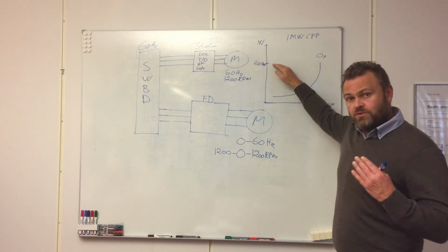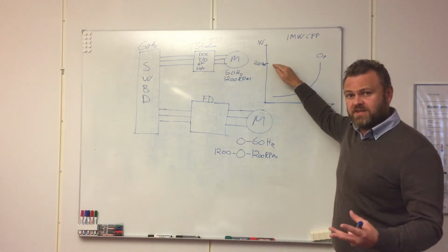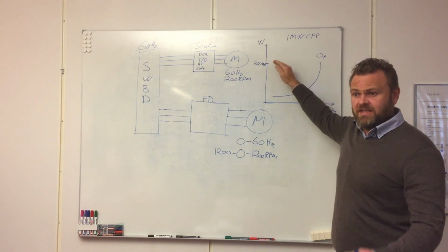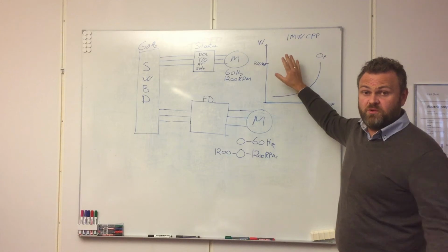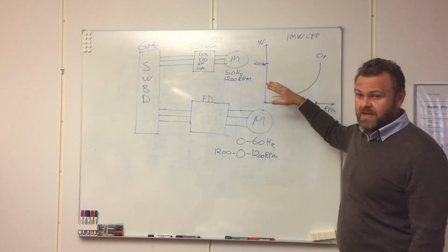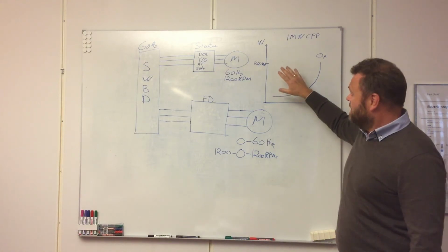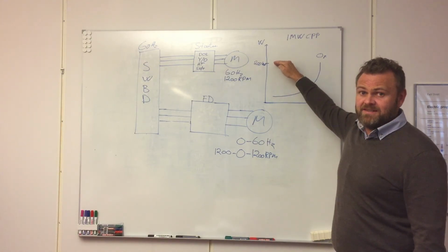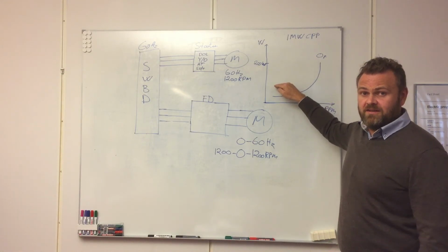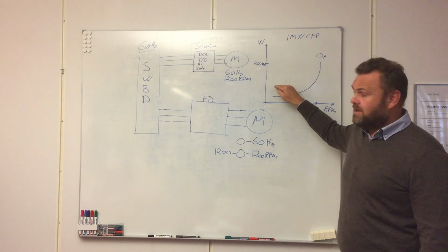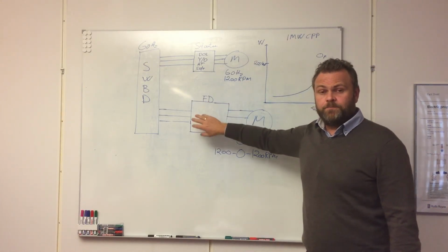So you have to look into the utilization of the equipment on board, what type of vessel. So if this vessel is a cargo vessel, just spending a few hours per week or maybe several hours per week, you have to look into that. Well, then maybe these savings, to save these 200 kilowatt, isn't really a big deal, looking at the investment for a frequency drive.